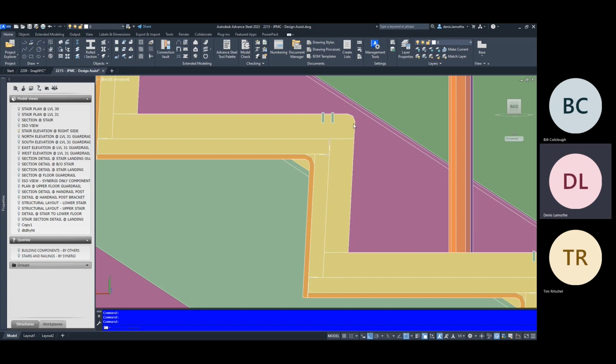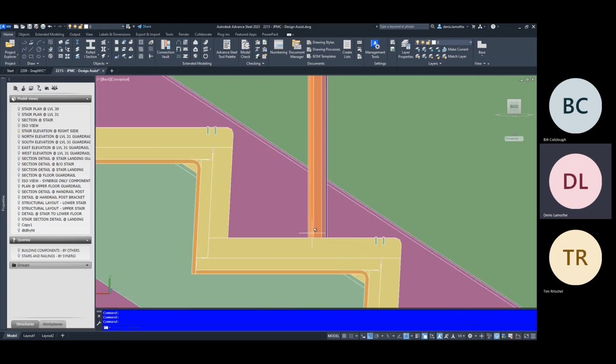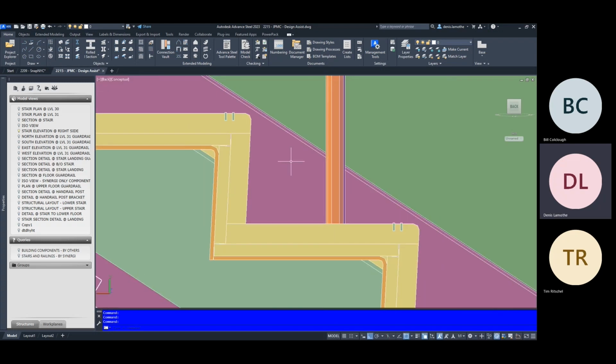Architects will typically have, on their drawings, at least a generic detail of a tread and riser component, and they'll show if they want a larger radius nosing or not. Most of them are pretty good at dimensioning that. Not all of them do, however. So if you do have to dimension something, it depends on the type of material you're using, if it's wood or precast terrazzo.